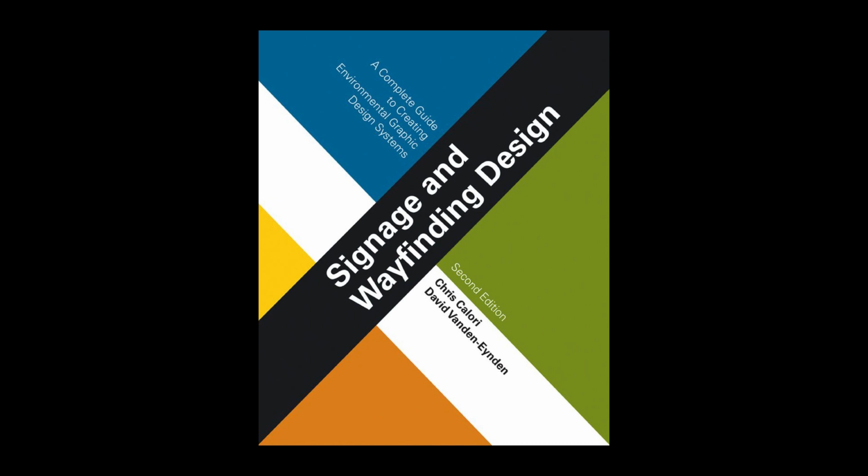The sign locations and numbers need to be clearly visible on the sign location plans, but this is easier said than done because plan drawings are typically cluttered with written information such as notes, dimensions, symbols, etc., which is necessary for construction of the project, but tends to obscure sign locations. Nevertheless, there are several ways to increase the prominence of sign locations and numbers. Always request clean base plans with the written information removed if possible.